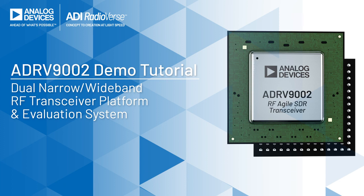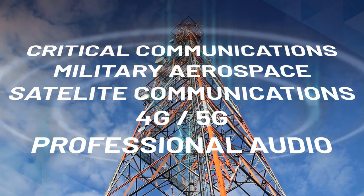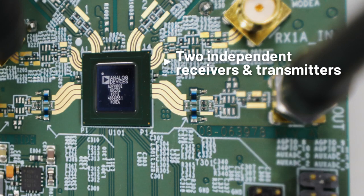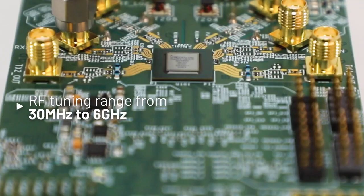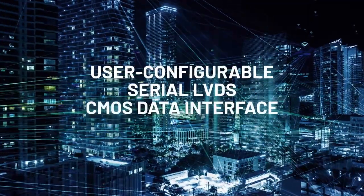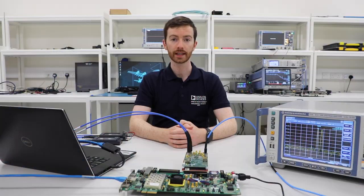The ADRV9002 is a dual-channel narrowband and wideband transceiver platform. It's our first narrowband and wideband single-chip FDD and TDD integrated transceiver. It has two independent receive and transmit channels and two independent on-chip RF LOs that can be routed to any of the receivers or transmitters. It has an RF tuning range from 30 MHz to 6 GHz and has a scalable bandwidth of 12 kHz to 40 MHz per channel. It has a user-defined serial LVDS or CMOS data interface and comes with signal correction algorithms or tracking calibration algorithms.